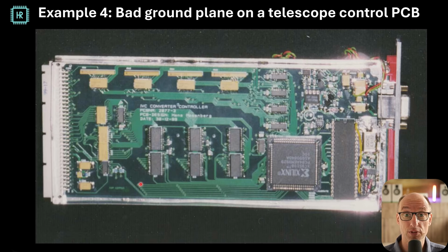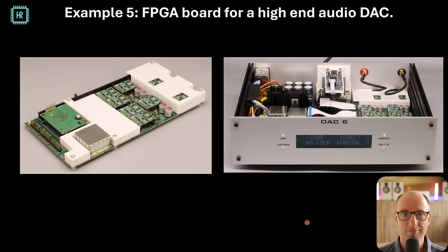So this is the first time I actually designed a 4-layer board. I just made a 4-layer board with a good, unobstructed single ground plane with ground vias for each ground, which are my main 2 rules, flipped it back on and all the problems were gone. This just shows you how simple it is. It's really so simple to prevent these issues.